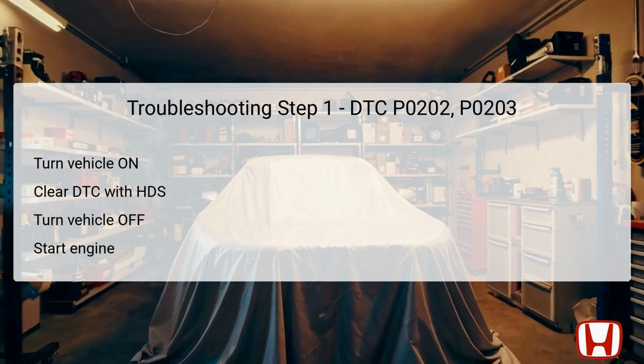The next step is to attempt to start the engine. If the engine does not start, crank it for about 20 seconds. Following this, check for any pending or confirmed DTCs again with the HDS. This process helps ensure that the codes are current and need further investigation.